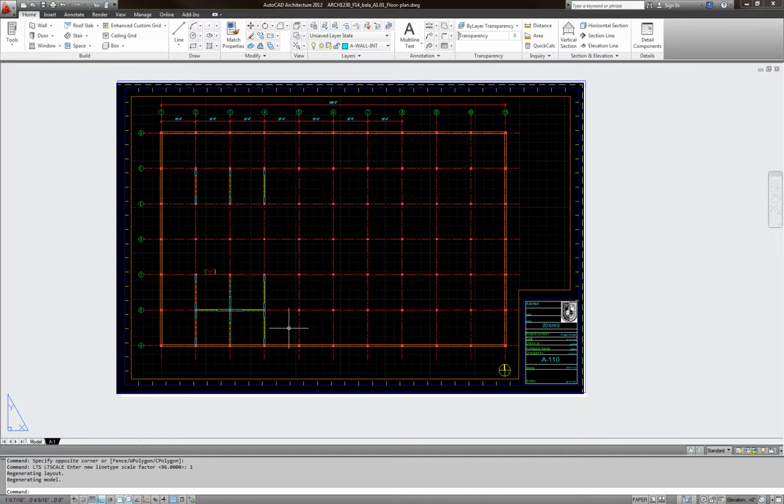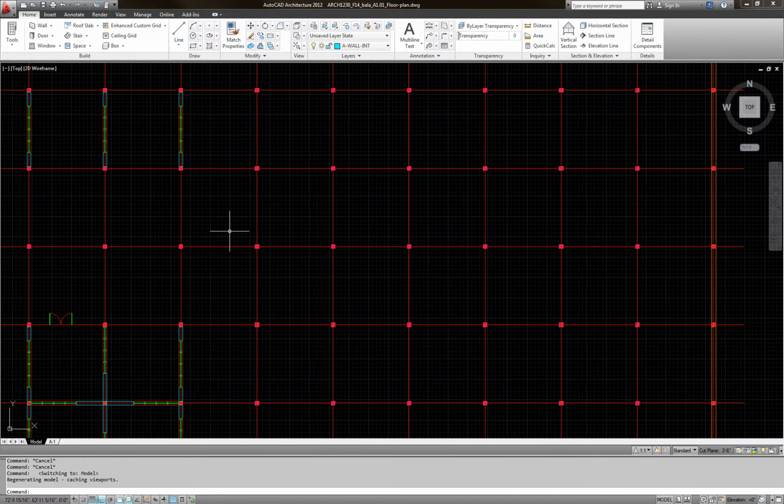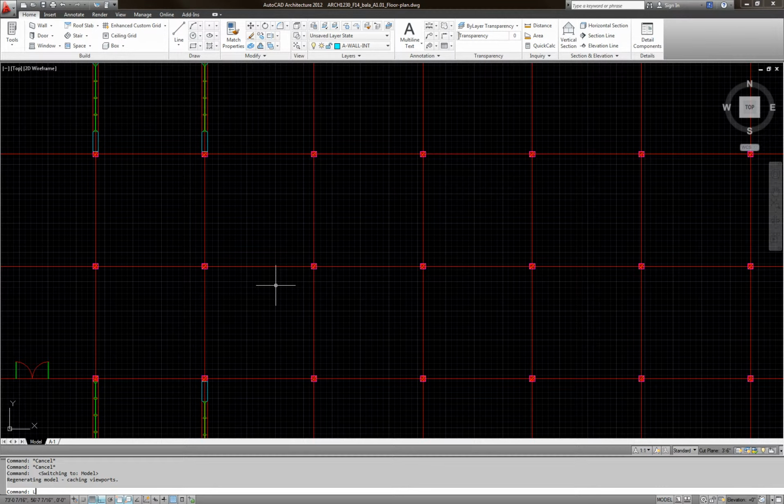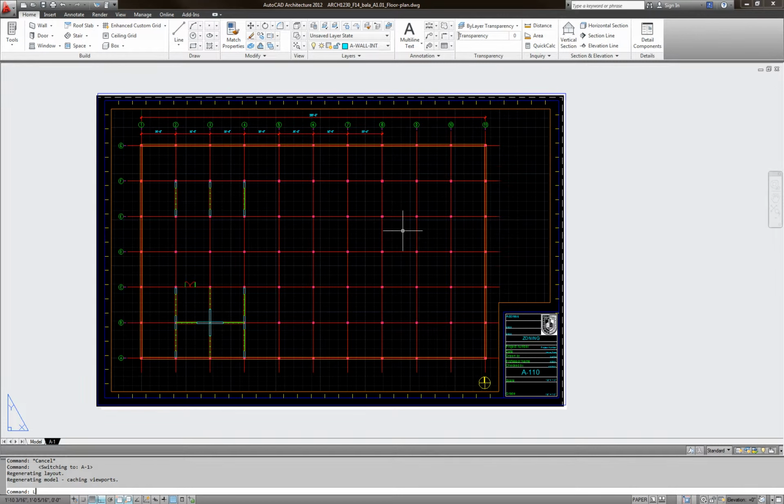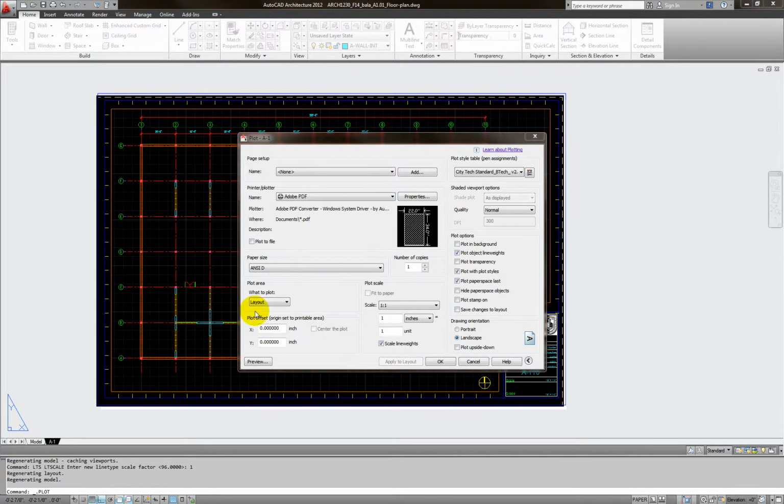Okay guys, and also do print preview, always print preview. Now when you work in model space, see that now the LTS is gone. So now type in LTS 96, you'll see. But when you go to the layout space, oops, it's not there anymore. So LTS 1, always in layout space, no matter what you do, is always 1. So now right click, plot. I'm sorry that I used all the shortcuts, but you can also use Control P.